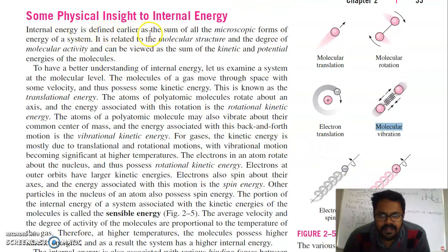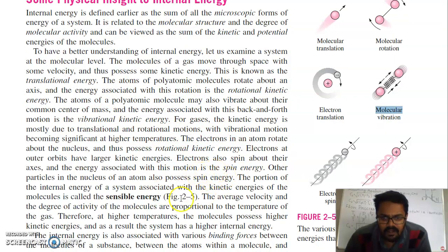Internal energy was defined earlier as the sum of all microscopic forms of energy. It is related to molecular structure and the degree of molecular activity. These activities can be viewed as the sum of kinetic and potential energies of the molecules. To have a better understanding of internal energy, let us consider all these energies: translational, rotational, and vibrational. The electrons in an atom rotate about the nucleus and thus possess rotational energy. The portion of the internal energy of the system associated with the kinetic energy of the molecules is called sensible energy.